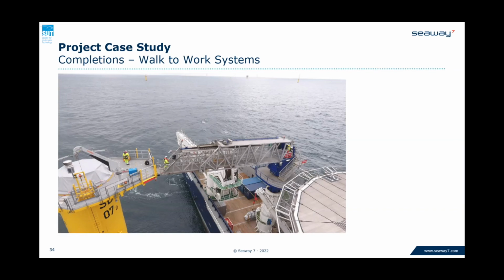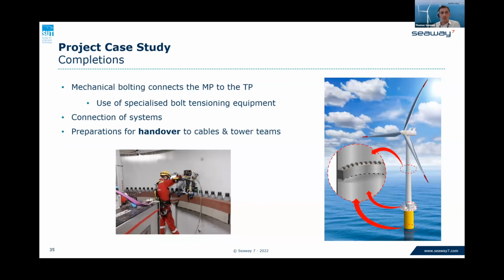Yes, we can. Perfect. So speaking about completions, what I mean there is the physical bolting or grouting of the transition piece to the monopile. And that can range in the number of bolts depending on the design and size of the monopile, but the ones I've seen can have in excess of 100 bolts. You can also see that there are other locations where that technology is used between the towers, the sections, and the TP, and also the tower sections standalone, but we don't get involved in that too much.